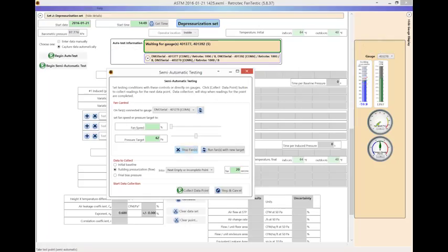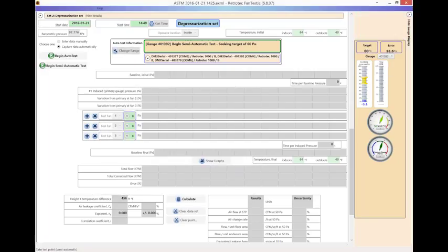It's quite possible that a tube might be disconnected on one fan, or the wire might not be connected, and you can run around and check all of your fans individually by simply changing the serial number over on the right-hand side for the display and over on the semi-automatic. So let's say, for example, you've got one fan at the top of a 10-story building. Instead of running back and forth or using radios or whatever, you can use this feature to run that fan throughout its range, check to see that it's working, it's giving results, shut it down, and then check the other fans before you press fully automatic. Does that make sense? It does to me.